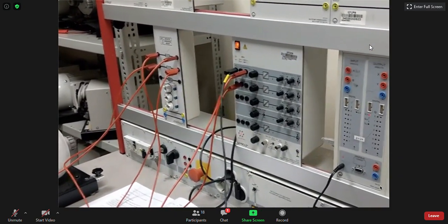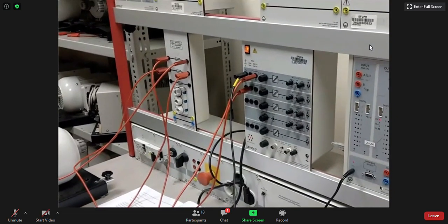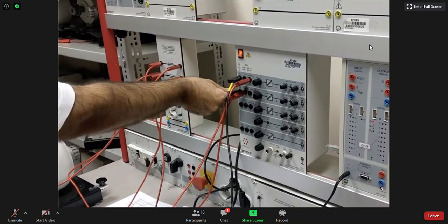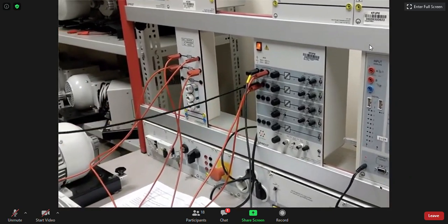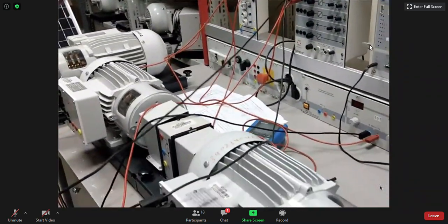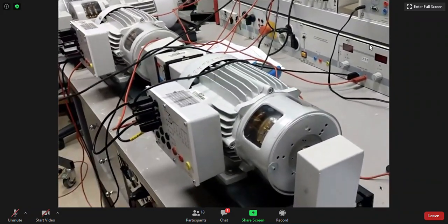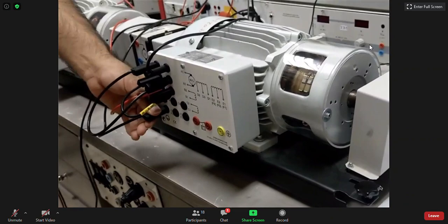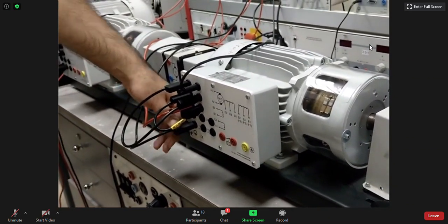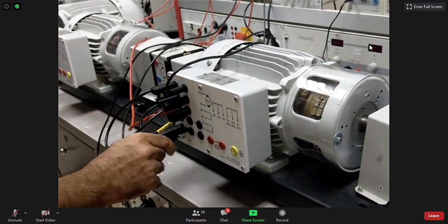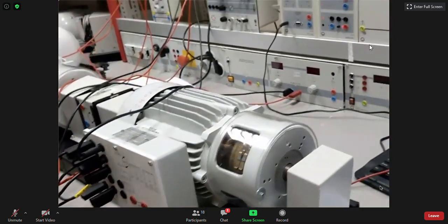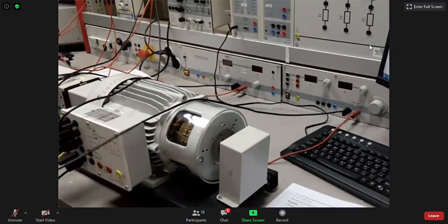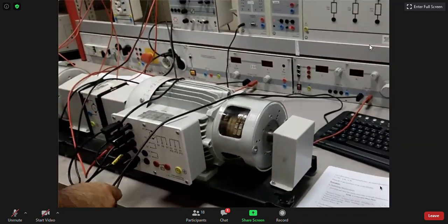So now, after we measure the current here, this is the ammeter. It will pass through the ammeter, and then it will come back to the machine, as you can see in E1. So E1 is the positive terminal of the field, and then from E2 it will go where? To the negative terminal of the power supply. Is it clear? Basically we connected the power supply, DC supply, to an ammeter.